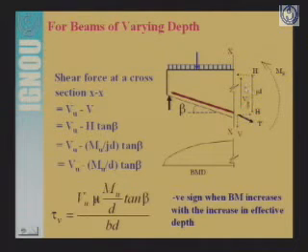Here Vu is the shear force, design shear force calculated under the design load. Here due to the variation of bending moment, this force H is coming. This H is the horizontal component of the tensile force that is coming in this bar. If we take the horizontal and vertical component of this T, then this is H and V.